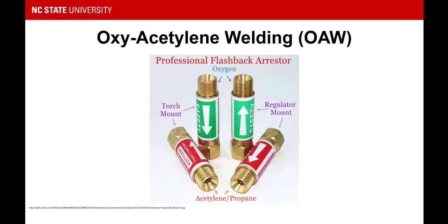So, oxyacetylene welding here. Here's what the flashback arresters look like. They're little cartridges that screw on. Pay attention to the color coding. Pay attention to the arrows. The arrows display which way gas flows through the setup. If they're attached backwards, gas will not be able to flow.